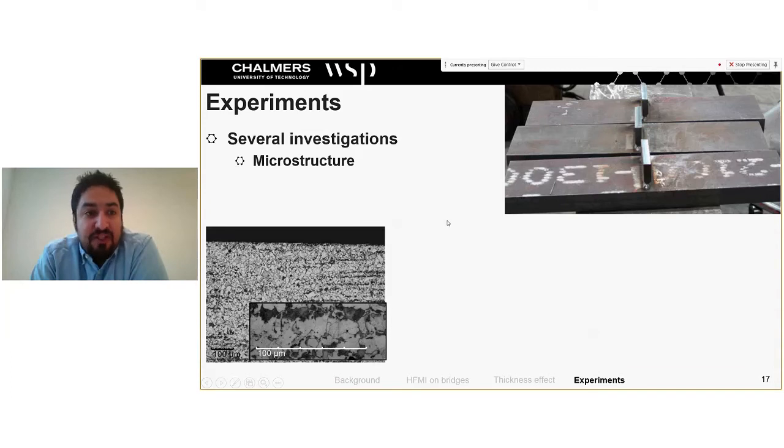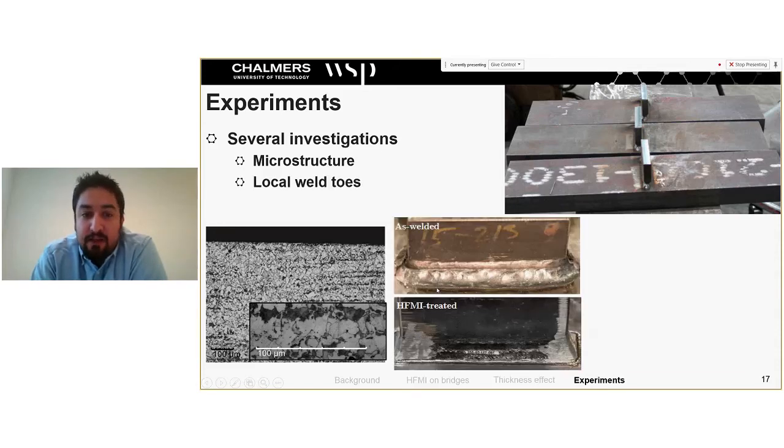We performed several investigations. We looked at the microstructure of these specimens at different regions. We looked at how the HFMI treatment changes the geometry at the sensitive area.